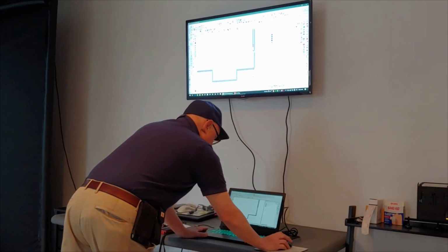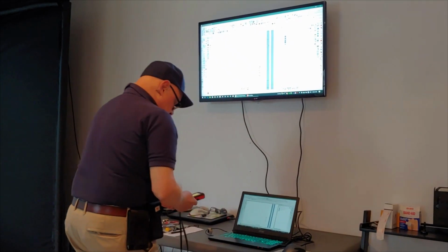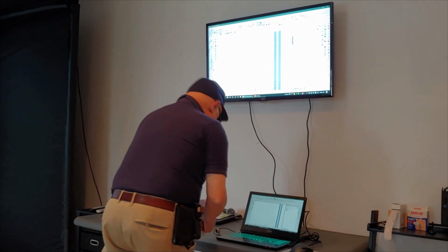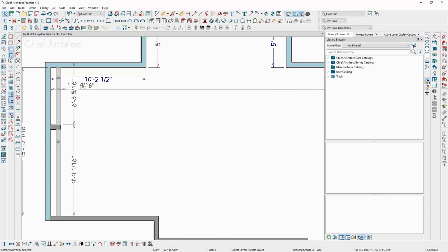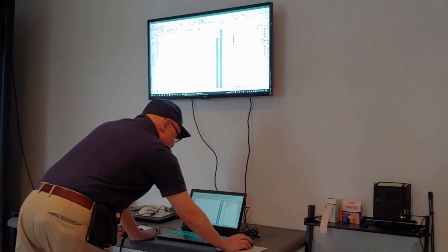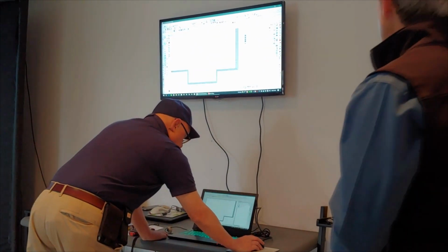That's the height. The next thing I have to worry about is the actual size of the shelf, and that was 8 3/8 inches. So I'm going to adjust a dimension here. I'm just going to use a temporary tag to do that. Take one of the dimensions, just put another extension on, and move this so that it's 8 3/8 inches, surface to surface. And let's see if I can just lock these two together, just like that. That looks like a pretty fast way, Al.